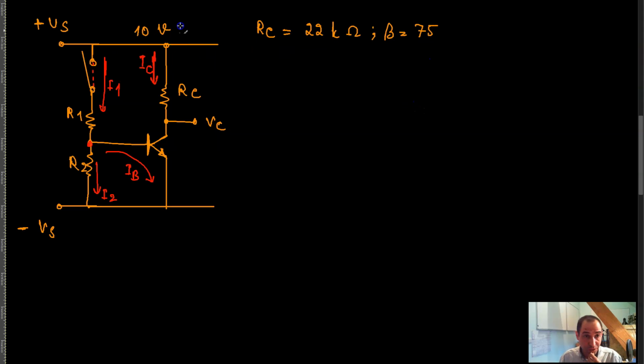And V_S is equal to 10 volts and so on. So again, you want to turn this transistor on, so I apply Ohm's law to this resistor R_C, V is equal to IR. I want the whole supply voltage to be dropped across this resistor. So I set this voltage to 10 volts, and the current for that I don't know.